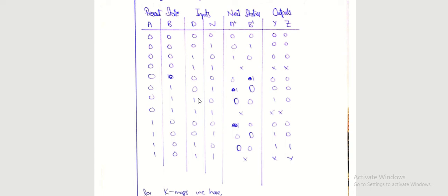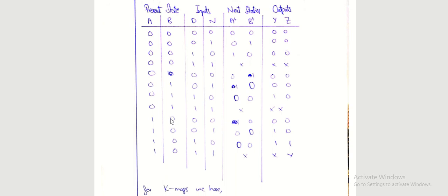Here if we input a dime, then we will release the candy, but there will be no change because we have received 15 cents and we release the candy which costs 15 cents. After this state we have 10 cents. So if the input is a nickel, we get 15 cents, we simply release the candy. But if the input is a dime, we get 20 cents. So we have to release the candy and also give the change. So both Y and Z are 1.